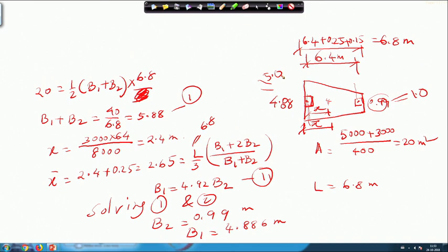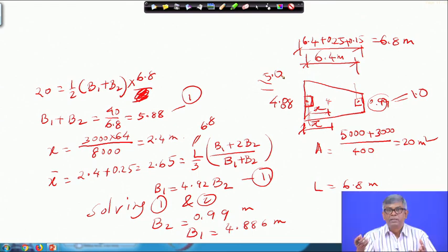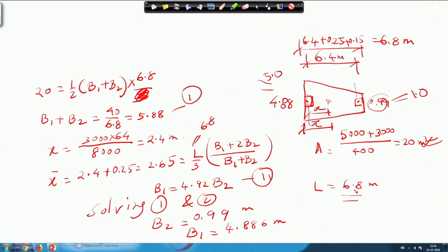So, that means this is the design of trapezoidal footing, that means both sides are restricted and columns are heavily loaded, and because of that we have to find out the dimensions. I know the allowable bearing pressure, I know the load. So, I can first find out the area required, and since the distance between the columns is known, and from the center of the column to the edge of the column and to the edge of the footing is known, those two quantities are to be added, and if I do that, then I will get the length of the footing.